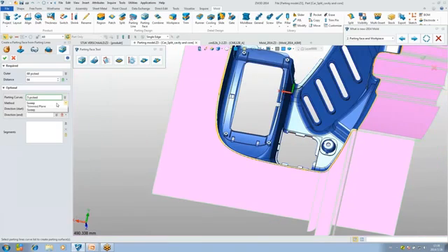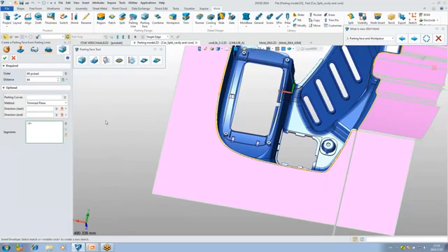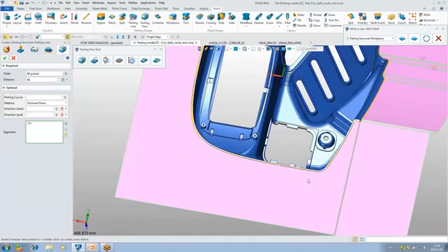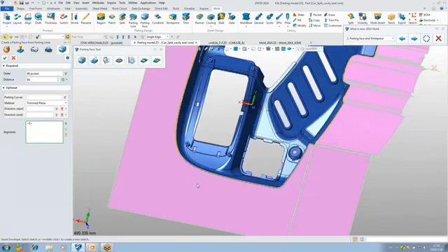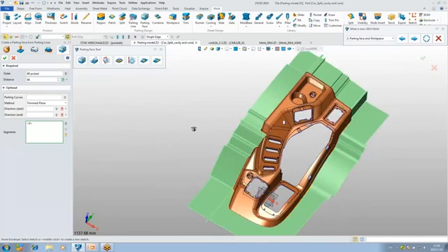And we use the trim plate command and set the direction for the start and end direction. Middle click. You can see the pattern face has been collapsed to one face here. It's much quicker in the ZW3D new version.